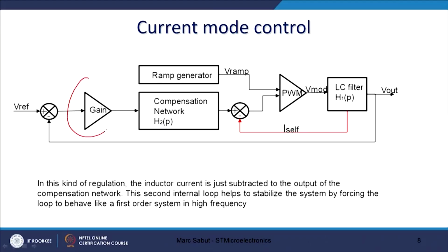Moreover, since it is inherently current control, it gives short circuit protection. So, let us see the block diagram of current control. This part is the same, and you can replace it with any type of PI controller already explained. This is basically the outer voltage loop, and thereafter you have a compensation network,